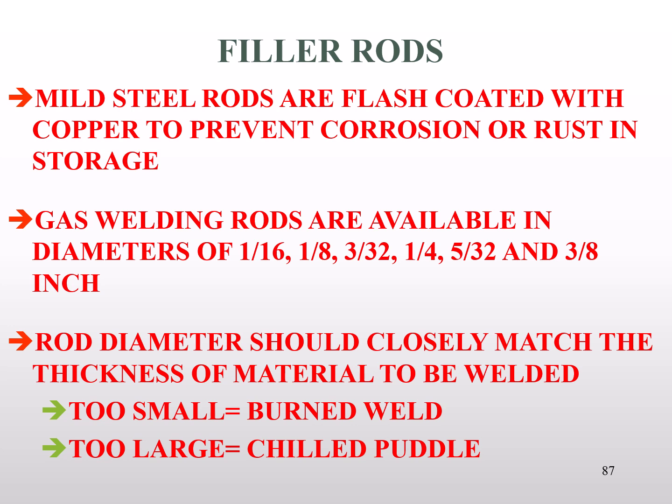And the question may come up, well, what happens if I take too small of a rod? Well, you're going to have to feed it very, very quickly to try to build enough filler up. B, it's going to overheat. When it overheats, it burns the weld. Your weld is too hot. It sinks in too deep. It has a rough and irregular finish on it. It's a bad weld. If I choose a rod too big for the workpiece, the moment I touch it to the puddle, it'll zap the heat out of the puddle, soak it into the rod, and just stick the rod.